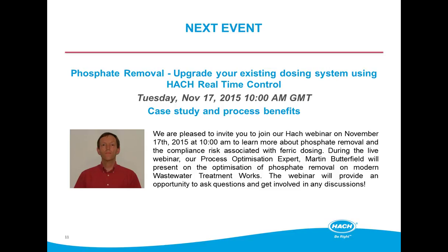And again, without understanding what the loading conditions are on the activated sludge plant, it's difficult to understand the treatment shortfall that's actually been experienced on the plant. You can obviously do mass balances and adjust for retention time to try and identify when you think the point source actually hit the works.